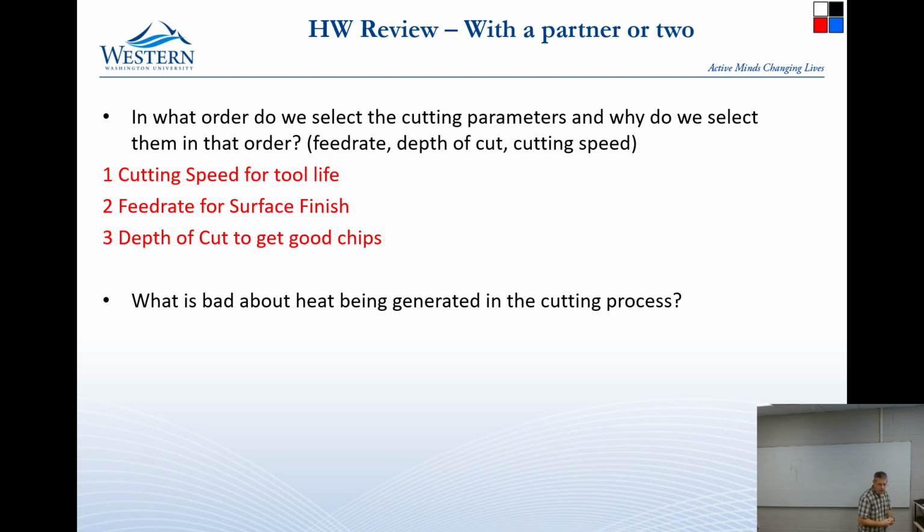The localized heat could make uneven properties in the material, like it could anneal at the surface. Yeah, it can do that. It can do a little bit of annealing in the surface. In general, it is so fast and so small that you can only really change the heat in the chip. You can't really change the heat in the body of the material to an amount that matters, mostly. You can certainly cold work the surface.